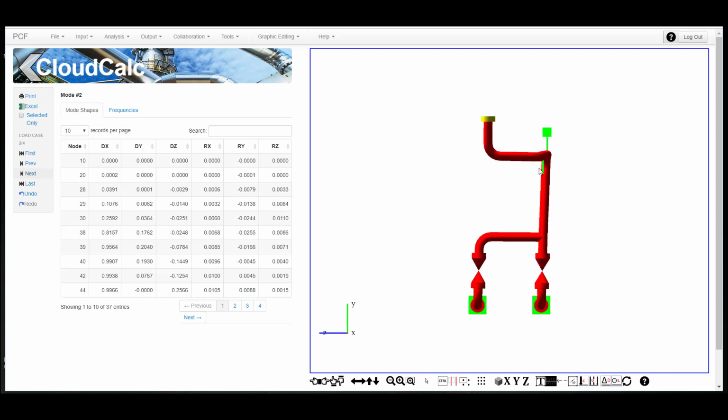The friction is not holding it down. And we know there's friction here because we have modeled it in. And how do we take that into account as far as dynamic analysis is concerned? Well, dynamic friction cannot be easily linearized. There's not a direct way to linearize it as far as dynamic analysis is concerned. So here we have to use a bit of a fudge factor.